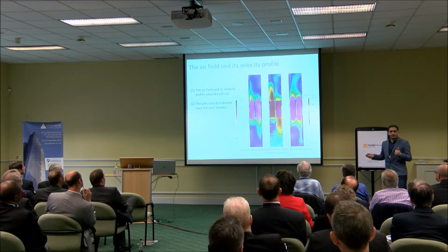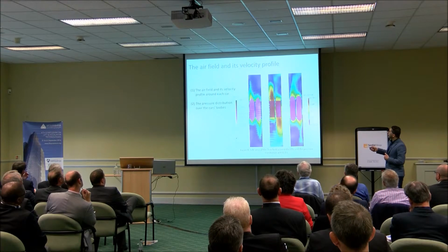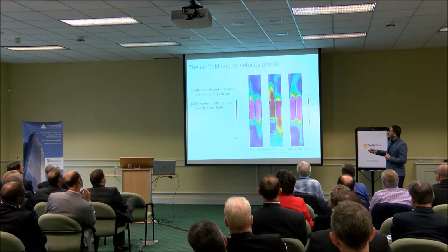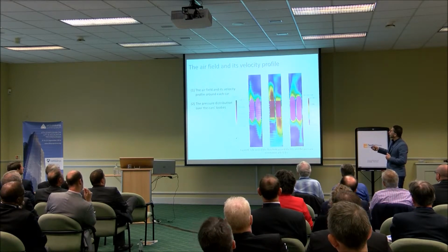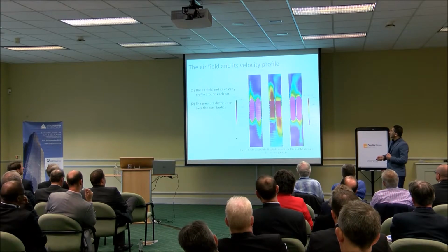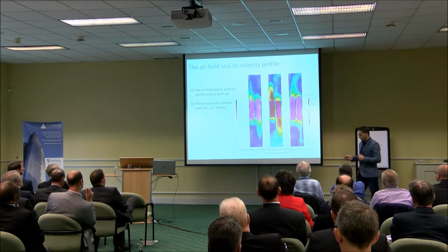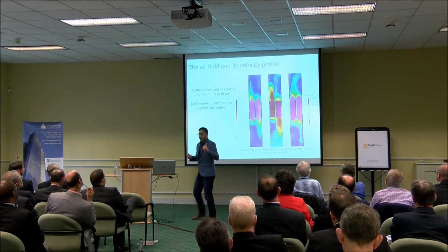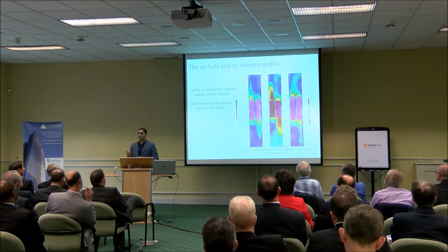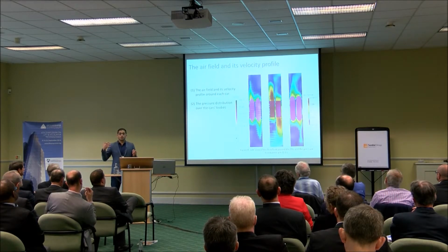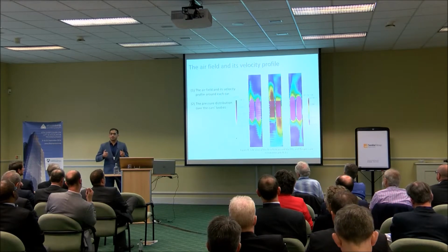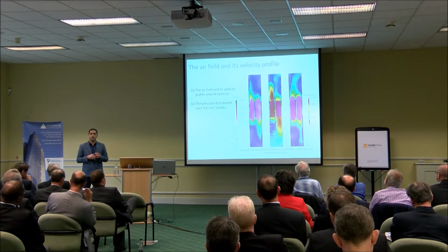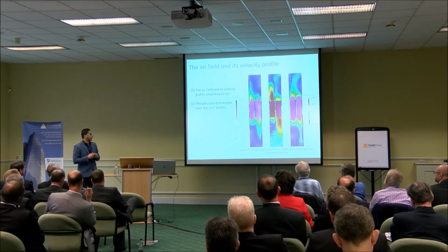Also, at the crossing event, it's clear that the air pressure acting on the triangular lift is less than the air pressure that acts on the hemi-cylindrical lift. I would like to say here that the pressure load fluctuation could cause noise and vibration which could transfer inside the lift cabin. This pressure would be building up and reaching its highest values at the crossing event, actually.